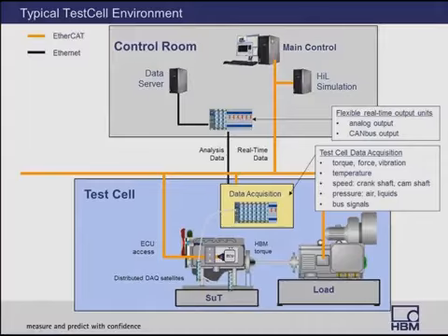You also have the actual computer, the control computer, which is running the data acquisition software, in this case D2T Morphe. And if your application requires some hardware-in-loop simulation, because in your dyno testing, you may have certain aspects of the application which are not developed yet, but there's a mathematical model that can work this aspect of the application. So using the software, you can run the simulation and in real time interact with the rest of the hardware, whether it's a system under test, the load, the data acquisition system, and do analysis, all using this EtherCAT bus.